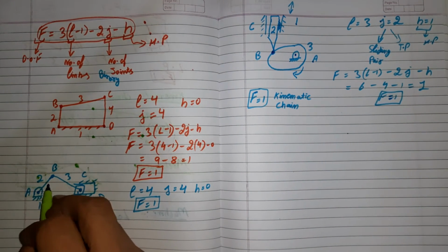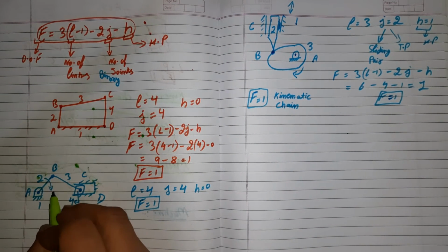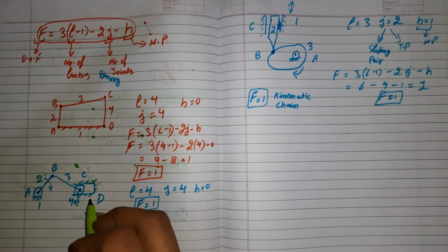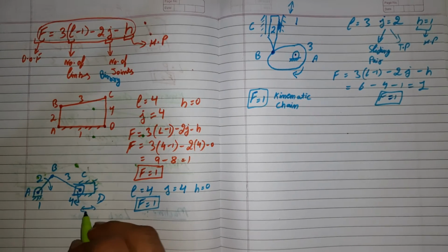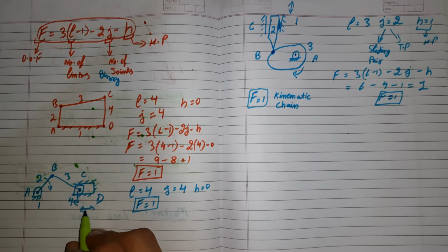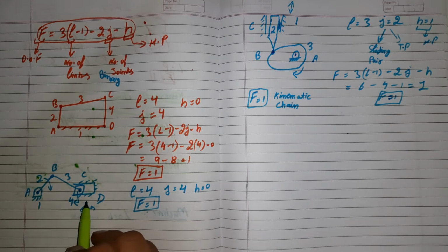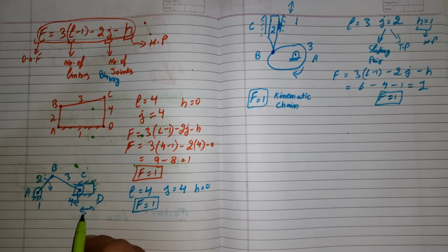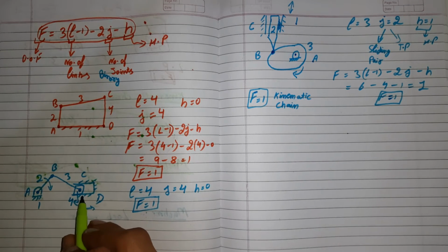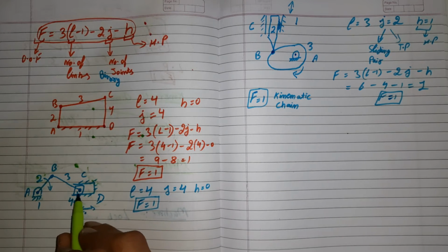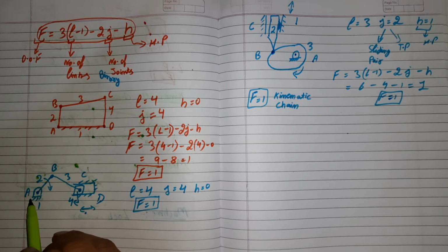Likewise, in this mechanism we have input as a rotational motion of the crank, and we have output as reciprocating motion of the piston. This is the basic structure of an engine. If we reverse it, like, we consider this reciprocating motion to be input, then the output we will get will be a rotary motion of this crank.